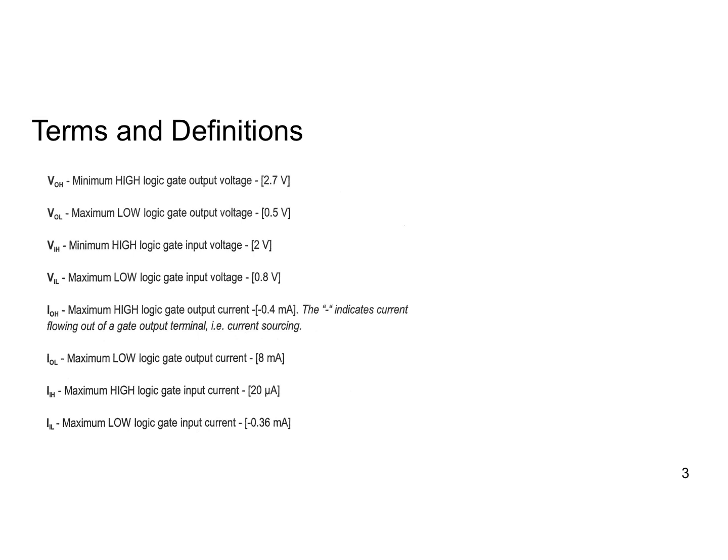It must be the cathode terminal, so it's current sinking. Of course, you can always go through a BJT transistor switch, which I've saved for the end. But as far as the gate limitations go, that's why it must be current sinking, which can handle 8 milliamps, which is adequate to illuminate the LED for us.